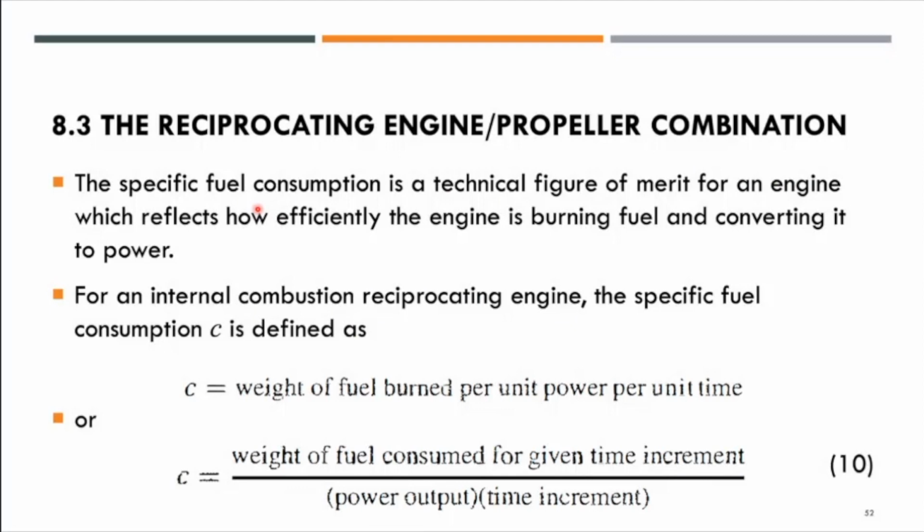If we look here, the specific fuel consumption, SFC, is a technical figure of merit for an engine. Normally when you want to choose an engine, you want to know the specific fuel consumption of the engine and how efficiently it burns fuel and converts it to power. For an internal combustion reciprocating engine, the SFC uses the symbol small c.